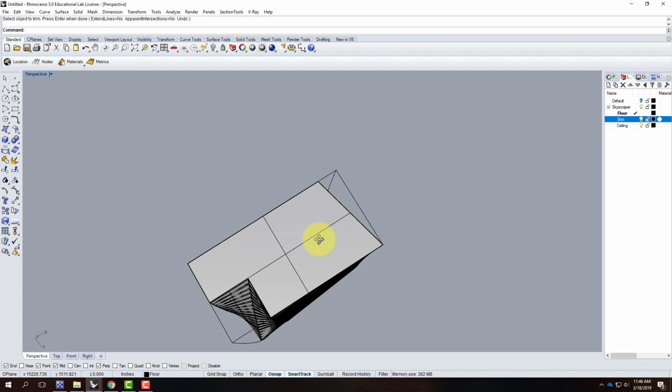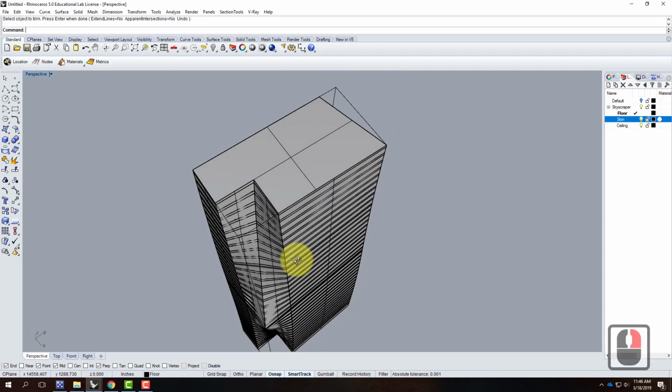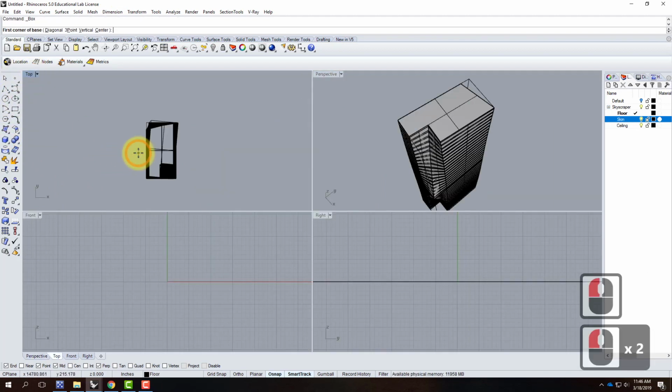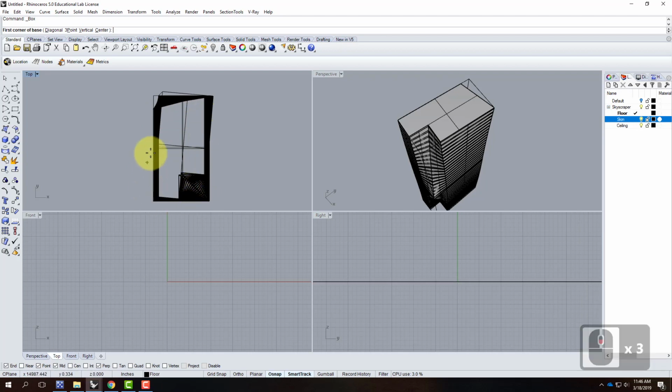If you're interested in this sort of thing, you're going to take 221 and do it there. So we're going to go ahead and cut all the way through the building with an elevator shaft or a stairway shaft. We'll call it just the core generically. And I'll go ahead and just create a box corner to corner. But sometimes placing the box becomes difficult. So I need to make sure that the box is completely inside of my building for it to work.